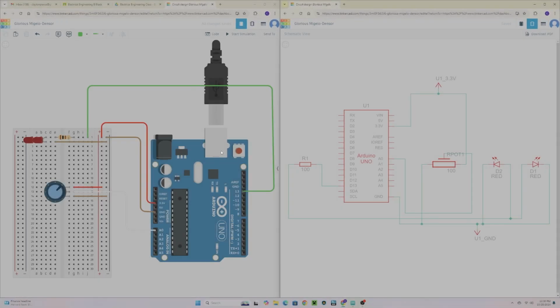This is the modified experiment number 3. The physical modification is an LED wired in parallel with the first. Otherwise, the schematic is similar to the first half, which shows the potentiometer being powered from the 3.3 volt pin. Here's the power right here.